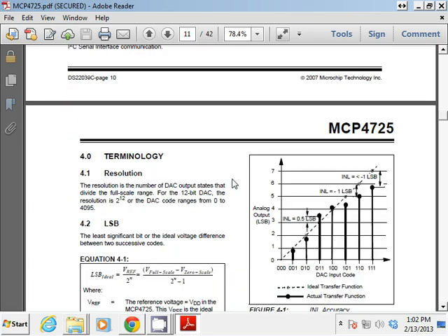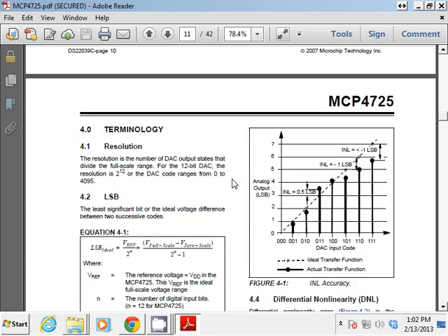Let's see, what else do we got here? Probably means you can have 2 of these wire-ORed together through the same I2C bus, and one would be wired to power and the other's wired to ground. After that, you'd have to start using some kind of logic to choose which one is going to respond, because they're each going to have a different address.